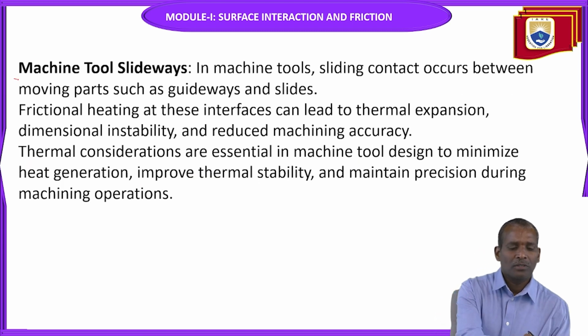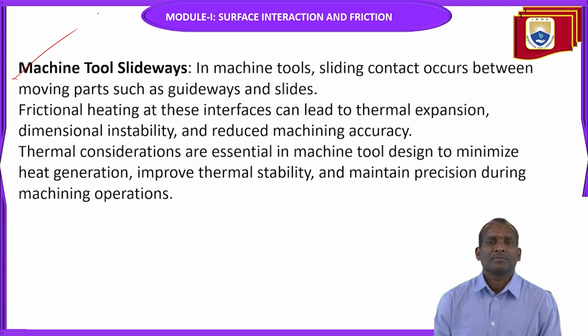Next, machine tool slideways. In machine tools, sliding contact occurs between moving parts such as guideways and slides. The frictional heating at these interfaces can lead to thermal expansion, dimensional instability, and reduced machining accuracy.